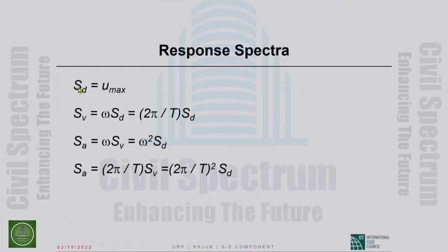So this spectral displacement is the same as maximum displacement. If we take our spectral displacement, 63 millimeters at half a second period, we take 63 millimeters, divide by the half a second period, then multiply by 2 pi, 44/7 roughly. The quantity we get has the unit of velocity. If S sub d is in inches, S sub d over T will be in inches per second. That has the unit of velocity. And this quantity is very close to, but not the same as, the maximum velocity of the single degree of freedom systems. So this quantity is called spectral